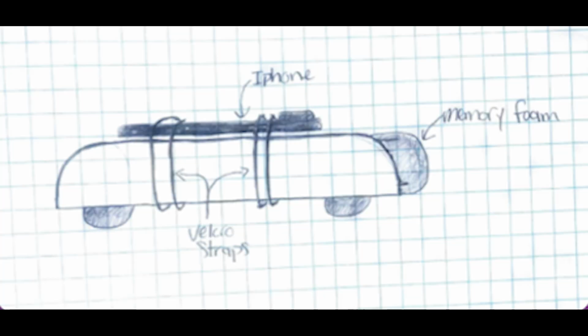Memory foam bumper. One of the first concepts involved a memory foam bumper. The design relied on foam deformation to increase collision duration and reduce peak impact forces. The advantages of this concept included low weight, simplicity, and easy manufacturability. However, repeated impacts caused inconsistent deformation behavior over time.